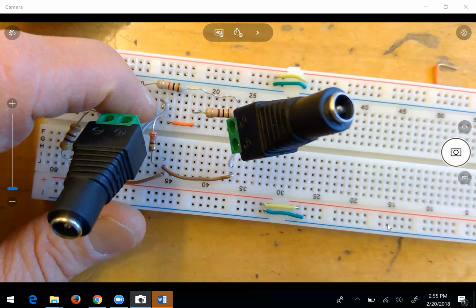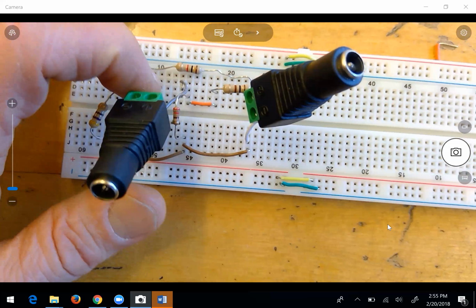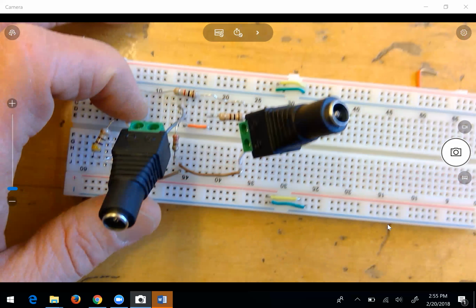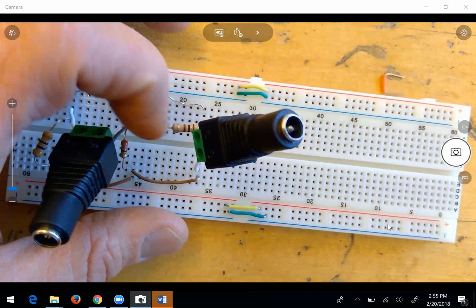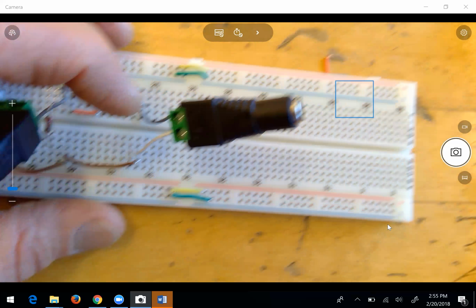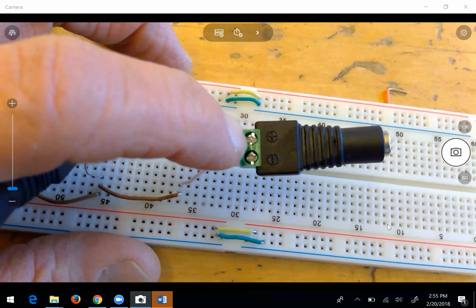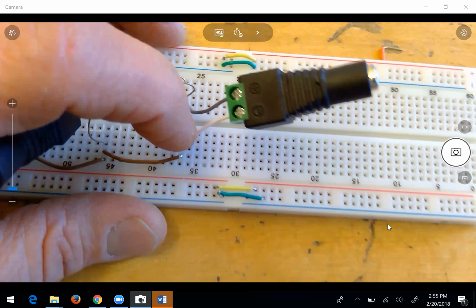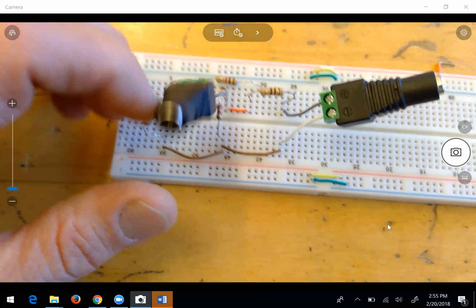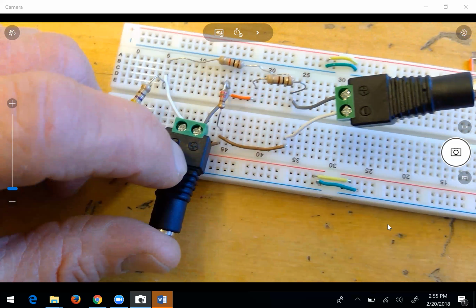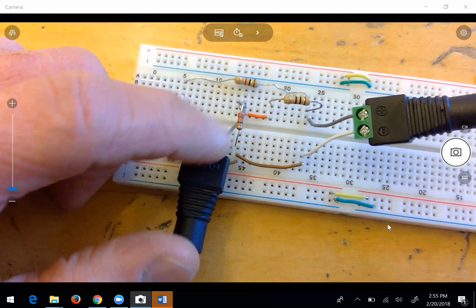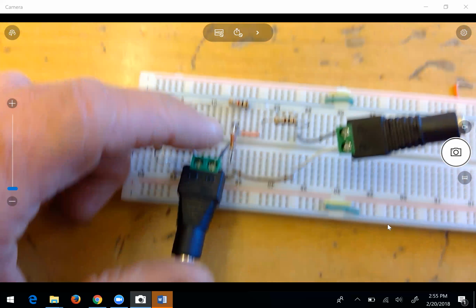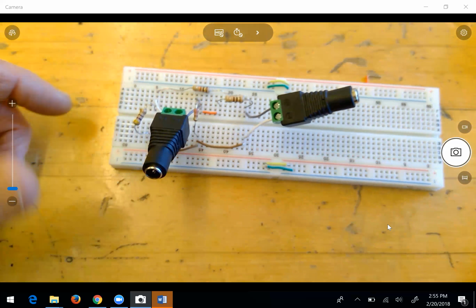And then you have, so that's your 220, the voltage source. And then you have your 100 ohm going to there, which, yeah, my recommendation is to change the color so both of these have the white on the plus side and the gray on the minus, just for consistency with the convention.